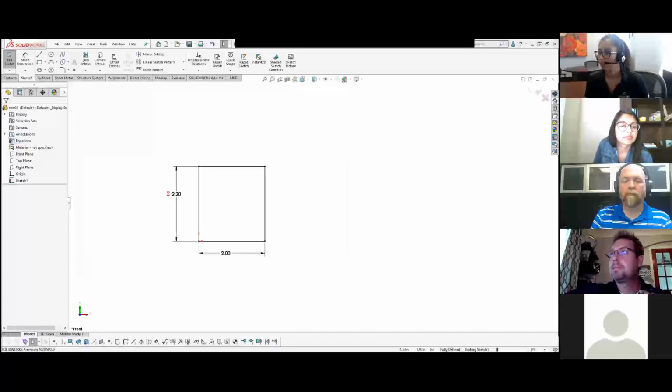Yep. We skipped one in the middle, right? How do you reset part sketch origin? Say I want to change the Z direction. Oh, like for people doing aerospace parts or something? Is that like changing the coordinate system? Is that what it is? I think so, like changing the front view, top view, right view. Most people that I see do this for aerospace parts, they just change their templates and they rename their planes.